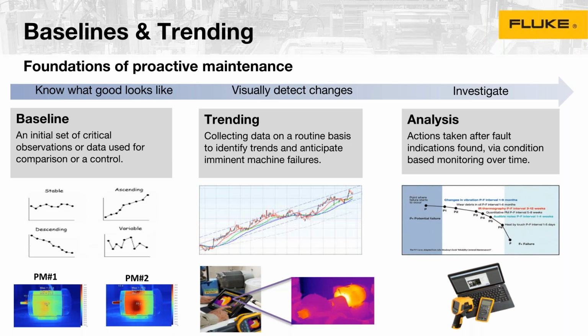That's how I try to present it to our customers. It is really great, and you can see the value over time in having, number one, what good looks like. I think that's a key, important factor. Often we say, okay, we have a bad problem, now we're going to start looking, but we never know what the reference was. I mean, if that motor is 155 degrees today, what was it 3 months ago? We may be still within spec, because we may think that it's overheating, but in reality, when you look at the spec, you're right in the middle of it. So it's important.